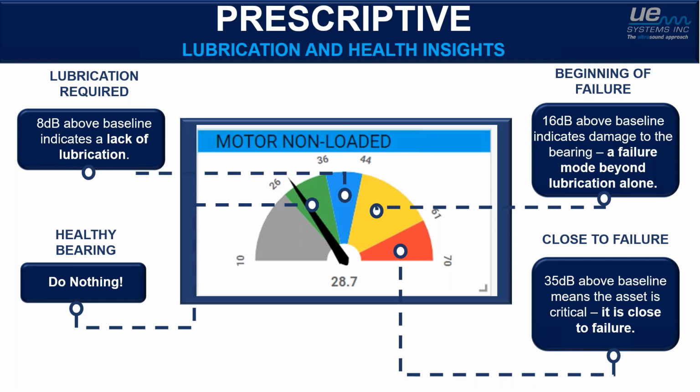Now, say you had the ideal sweet spot and you got that friction down to 26, and you kept lubricating, kept squeezing grease in, or kept telling that single point lubricator to put more grease in. You would actually see that arrow start to skyrocket to the right. It's going to blow past the green, blow past the blue, and end up in the yellow somewhere. That was exactly the chart that Mark was showing: you can get to a point where you over-lubricate, you get that fluid friction happening in that bearing, and start to pick up the friction level as well.